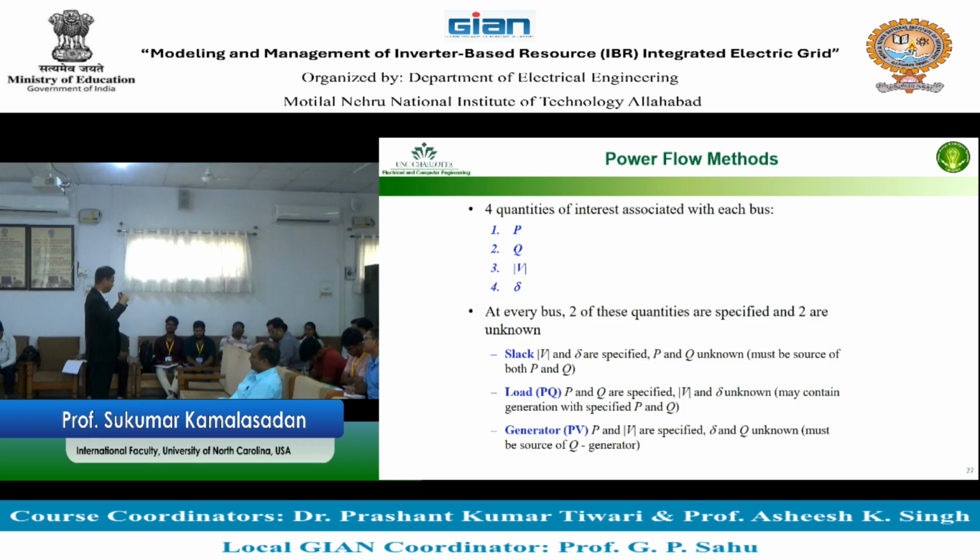Layer meaning there are different layers. Above the generator, there is a layer called automatic generation control, called AGC. Then there is a layer called load frequency control. This is basically done with AGC and some other things called tie line control and all that. It's like a story, it's not a part of this course, so we're not dealing with that. But the governor is used only at a fundamental unit level to control the speed as well as the power going out from the generator.